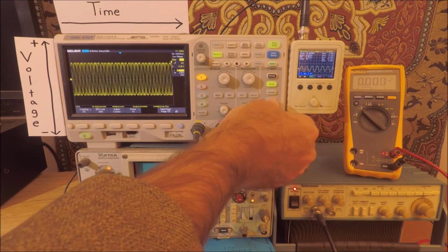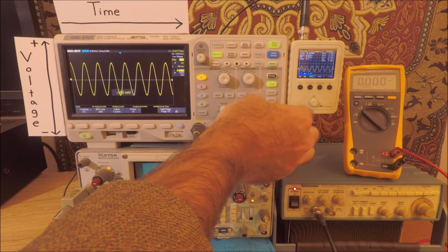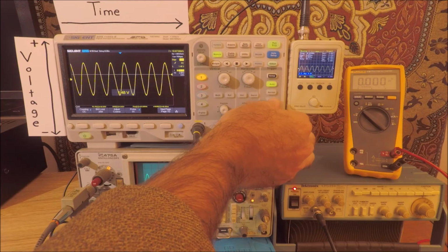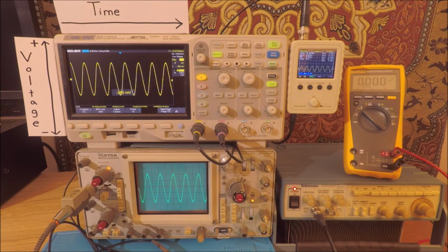So you'd come over to the trigger control and get it within bounds of the peak-to-peak voltage on that signal. Anywhere in there is fine. And now we have lock onto our waveform. We can also set up the trigger control to view non-continuous waveforms, and I'll show you how to do that in a bit here. But for right now, we'll just consider these continuous waveforms.